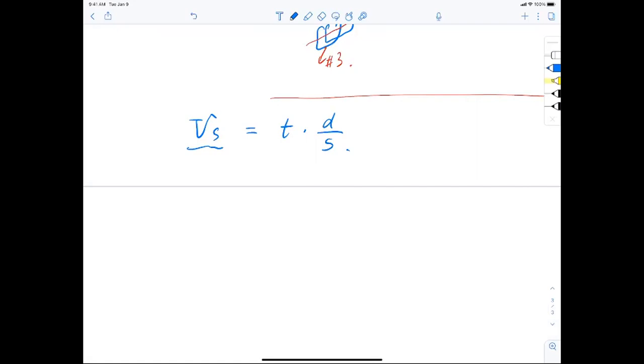Why is that? Normally, the bar size for stirrups is fixed, either number 3 or number 4. Nothing you can change about it. You use whatever is available to you. But the critical parameter we can change is the spacing between stirrups. So I do this because it exposes the parameter s in this equation, so I can design for it.